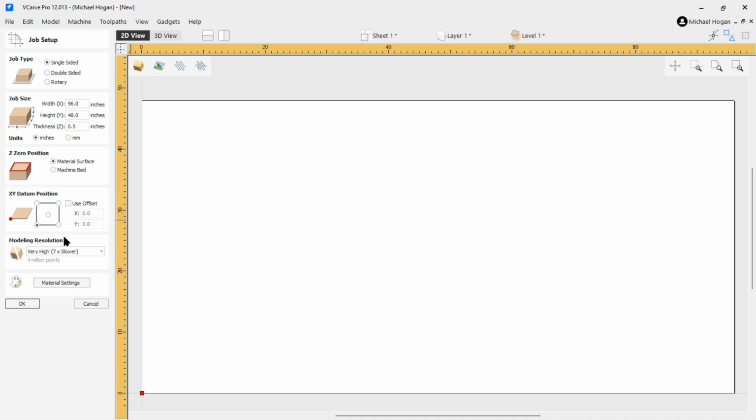They have to be the same way, or else they'll be scattered about in the drawing area and you'll have to reset everything. So it's important to remember how this was set up when you go to import your DXF files. We create one this way. You want to create it the same way when you import it.